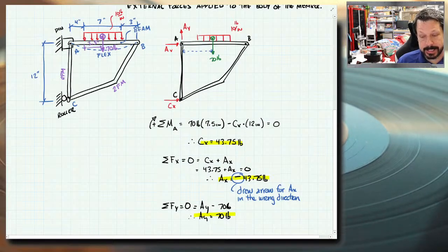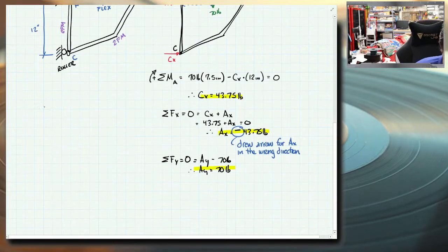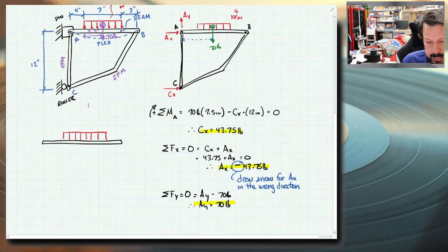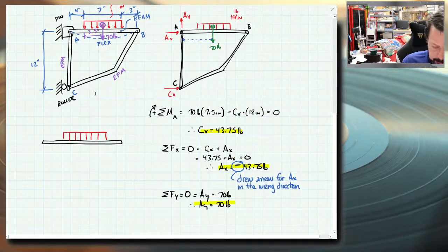Then it comes apart into, in this case, 3 different pieces. You draw the free body diagram of each of those pieces. So we'll start with AB. AB is just a horizontal piece, and it has this distributed load across it, and it has a pin, and so it has a couple of things. Let's look at B first.